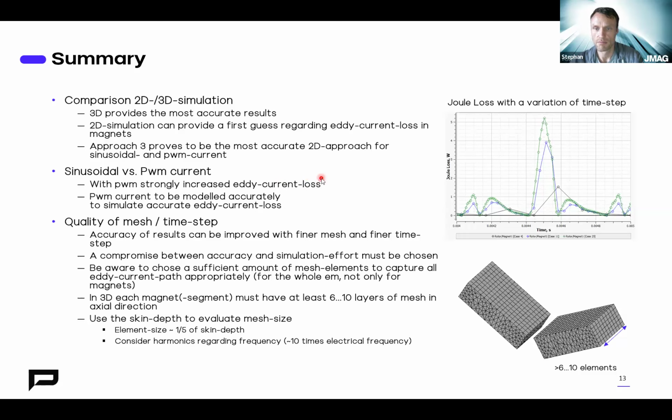But I think, as soon as possible, one should really consider simulation with PWM current to really assess the characteristics of the e-motor, especially regarding thermal design. And if you start to think about the cooling concept, then really start to do simulation with PWM.